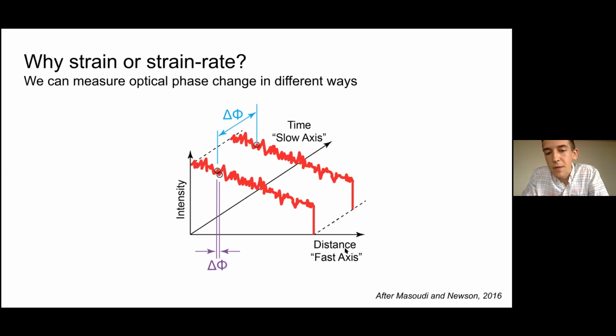Whereas if we repeat the pulse experiment, the next laser pulse that goes into the fiber might go in 1,000th of a second later. So we might sample this cable at 1,000 laser pulses per second. And so the second pulse actually is very slow compared to the first; the time it takes for all the light to return is very fast, microseconds.